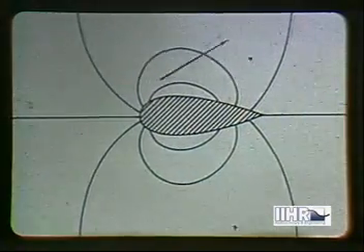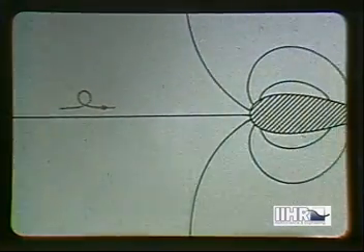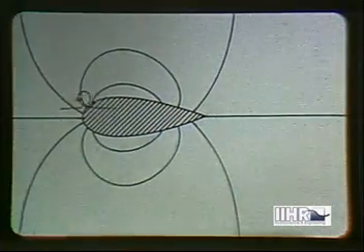If, instead of the fluid moving past the stationary foil, the foil moves through otherwise still fluid, a totally different pattern must prevail. Now the streamlines are displaced with the body, and the velocity vector hence varies not only with relative location, but also with time. The moving streamlines show only the instantaneous direction of motion at each point, and the path line of a single particle deviates considerably from each tangent streamline. The streak lines produced by dye released at fixed points are distinct from both streamlines and path lines, except at common points of tangency.